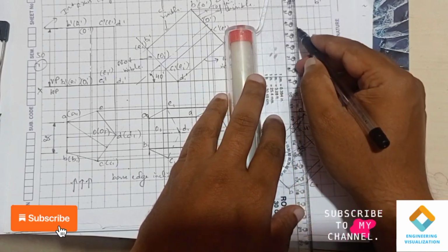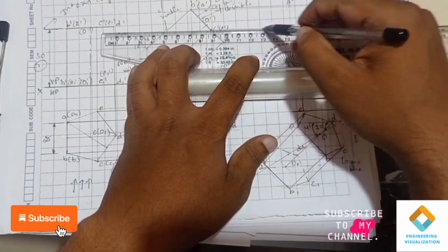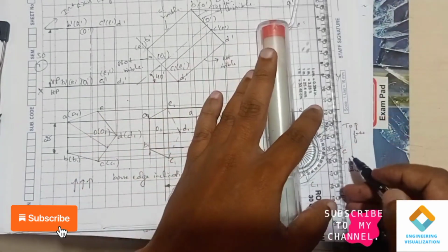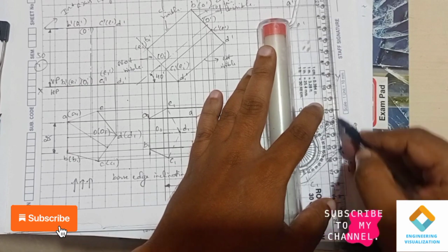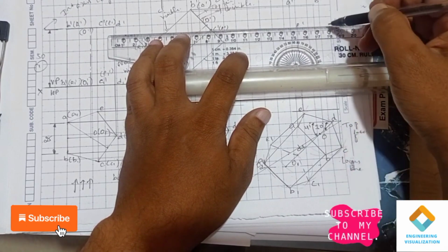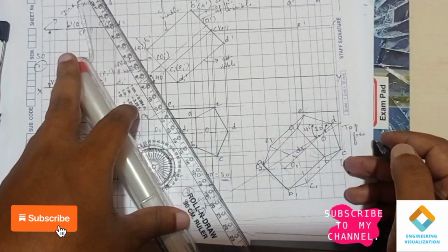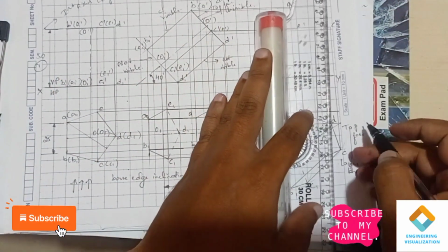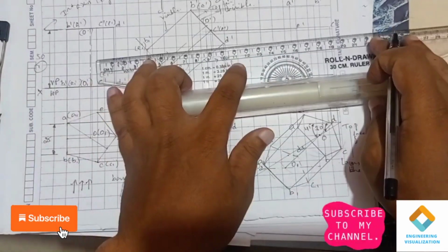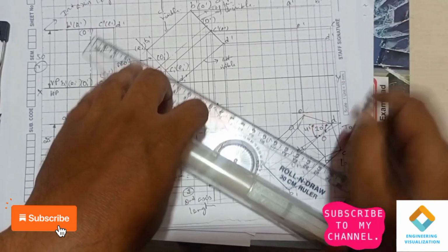From E also you draw the projection line. That is E dash. Same way you draw the projection line from that C end. Okay, draw the horizontal line properly. That is your C dash. Okay. Now same way we need to construct D here. D and D dash, where it is merging, we have to see. D and D dash merging at this point. This we call D dash.